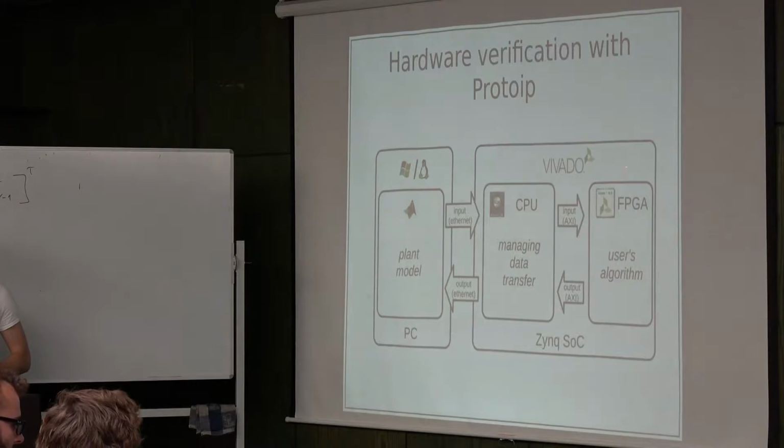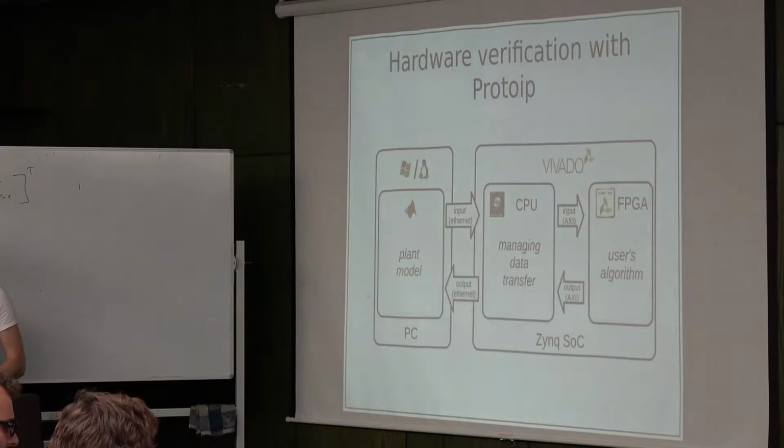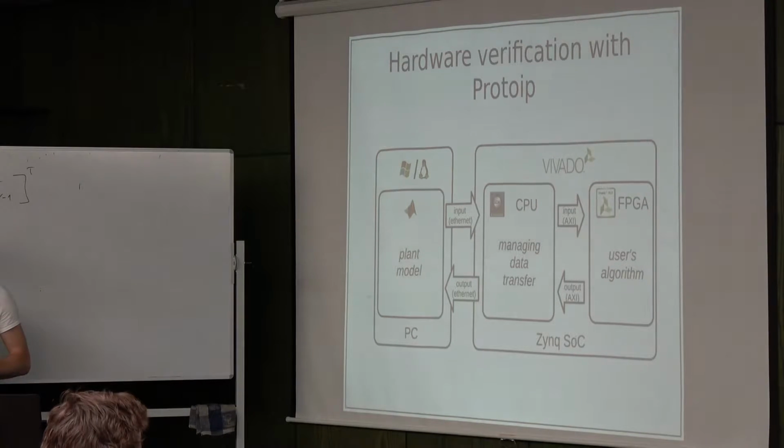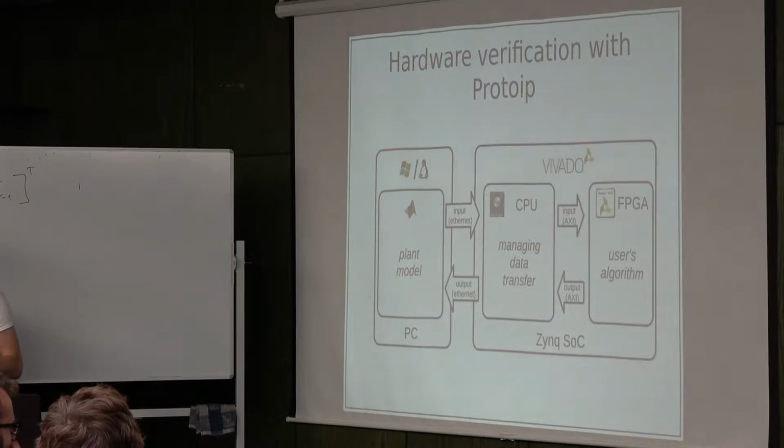Coming from the architecture, we have the Zynq SoC, our Zynq platform, which has a CPU and FPGA on the board. So what will we do? Sorry, could you speak up, please? Yeah, sure. We will use Vivado HLS in order to convert our C code into VHDL. Vivado HLS generates both VHDL and Verilog, but we will be mostly using VHDL.